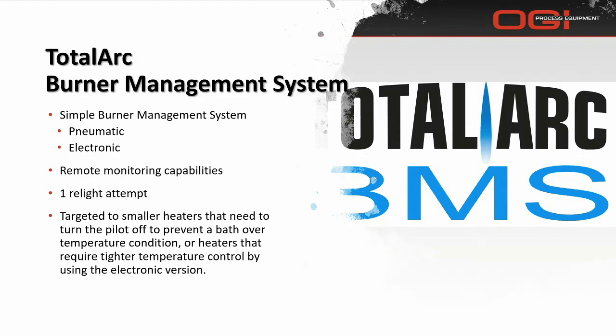We offer the same kind of remote monitoring capabilities with a dry contact relay and one relight attempt in the case of a flame failure. These controls are actually oriented towards smaller heaters that have such a small thermal mass capacity that even keeping the pilot on could cause an over temperature condition of the high bath temperature shutdown.